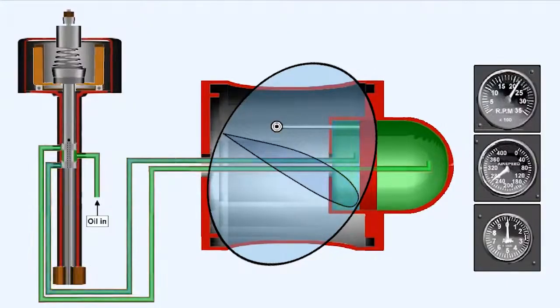As the RPM regains its previously selected value, the movement of the landed valve in the constant speed unit, which directed the oil flow in the first place, is progressively reversed until it regains the sensitive position, where a hydraulic lock holds the position in the pitch change mechanism immovable, until the next RPM selection or disturbance in airspeed, altitude, or engine power setting.